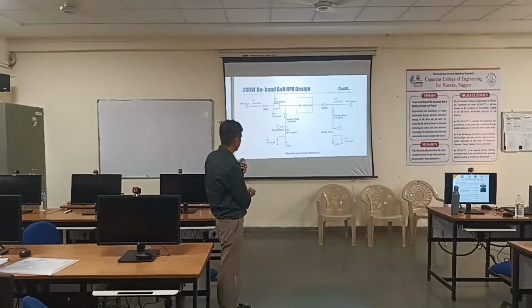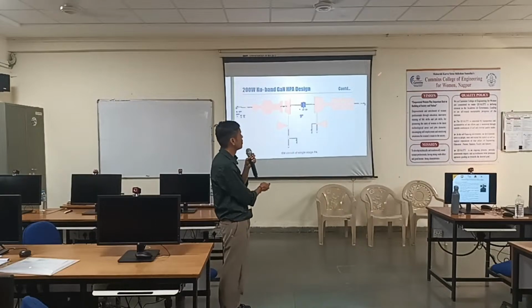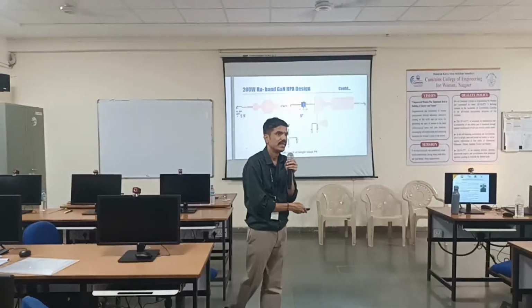I did parallel cascading. This is one stage. See, all the bond wires connected together. Input matching network, output matching network. But still it will not give me 150 watt. It will give me 90 watts.